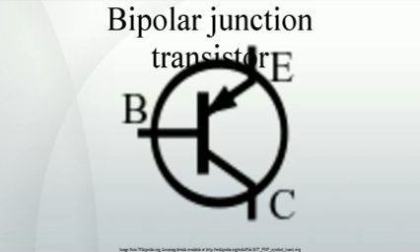Vulnerabilities. Exposure of the transistor to ionizing radiation causes radiation damage. Radiation causes a buildup of defects in the base region that act as recombination centers. The resulting reduction in minority carrier lifetime causes gradual loss of gain of the transistor.